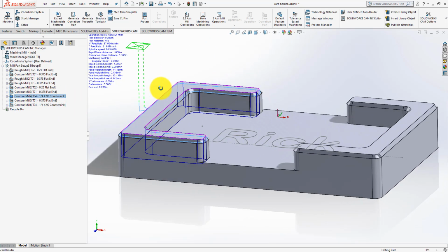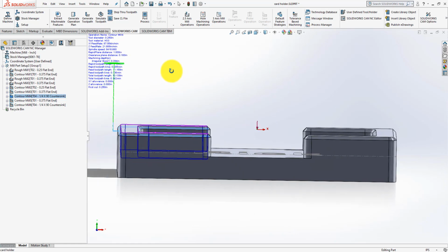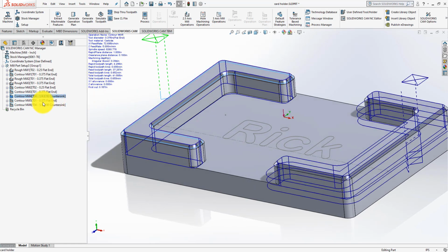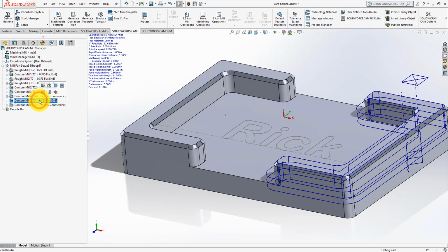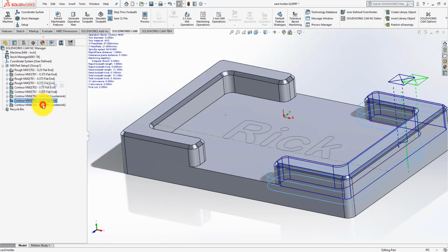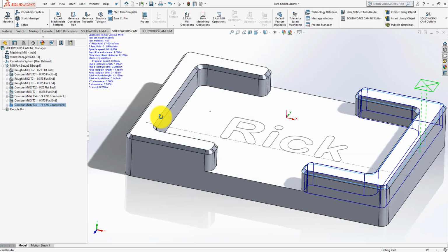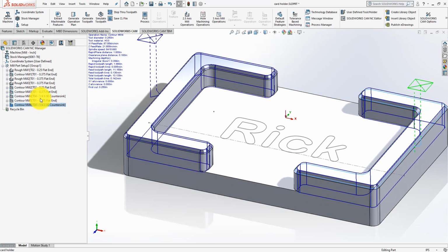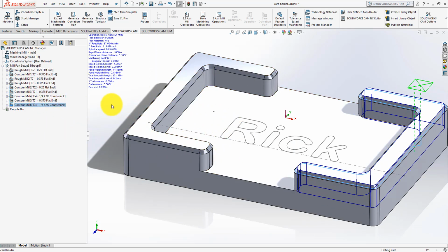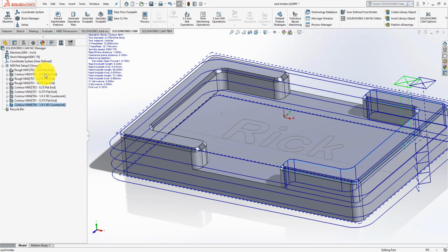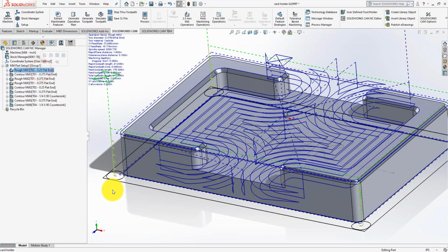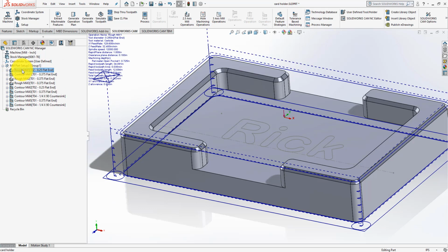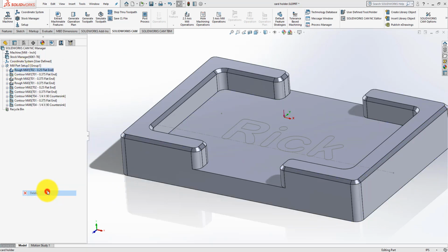Got our countersink, chamfering that edge. I'm going to look at that in a little more detail. 3/8 clean up that. Countersink chamfering that edge. Okay, so what it didn't do is the engrave, and it looks like the chamfer needs to be fixed up a little bit. And some fix up here is inevitable. This tool path here, clean up this corner, I don't really need this at all. So let's just go ahead and delete that one.